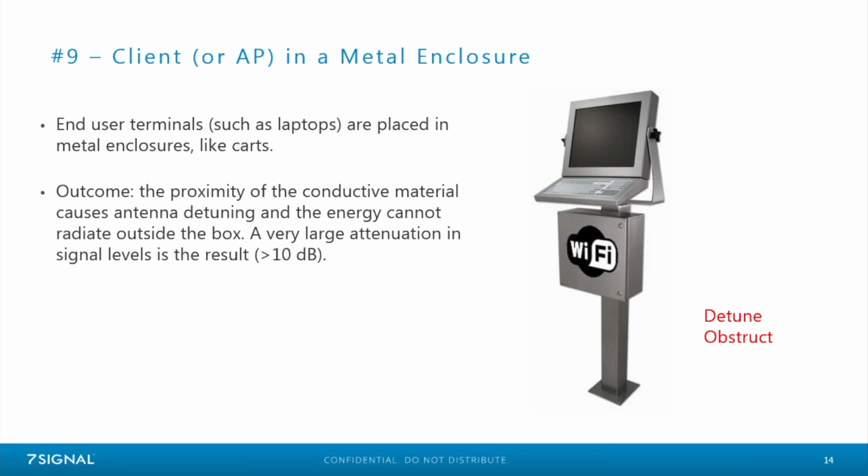Yeah, and sometimes the antenna manufacturer might have recommendations on specific paints that they have found in their own testing are safe to use. And sometimes there's a desire to paint an AP with internal antennas. I've seen that quite a few times, particularly in areas where they want them to be unobtrusive in a dark area. They just want to have black APs, so they kind of disappear.